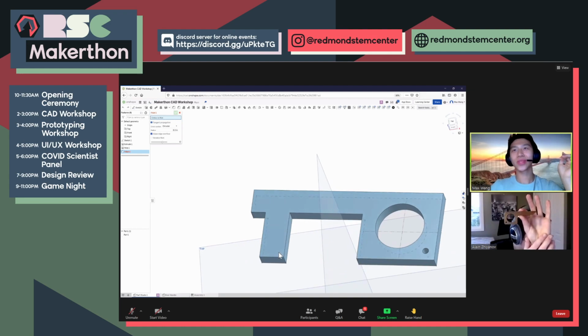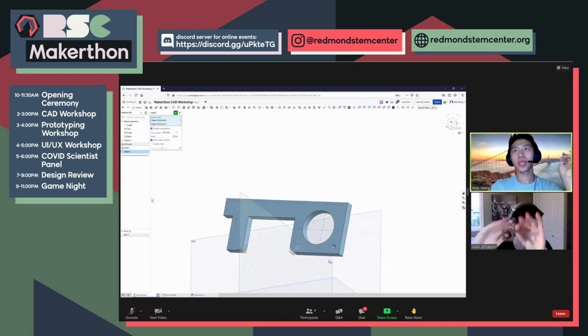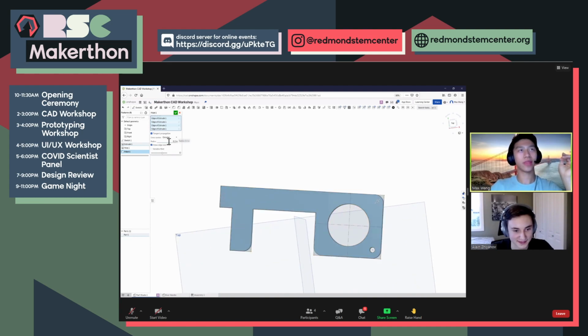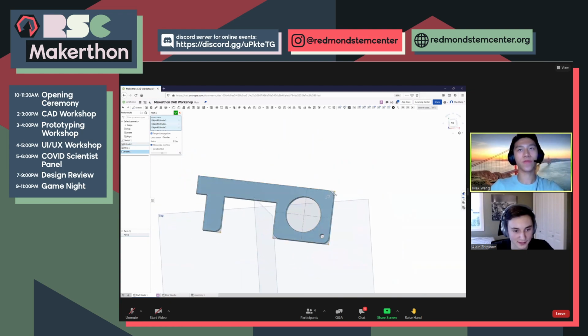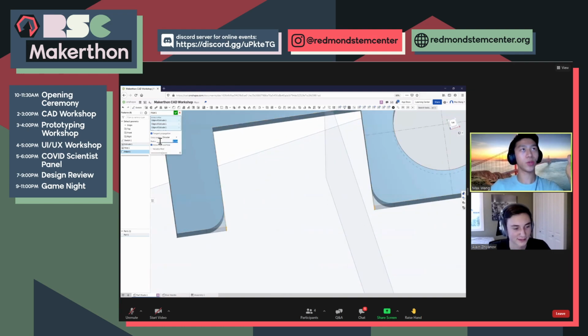So it looks like we want to fillet this edge, this edge, this edge, and this edge. Yep, those look okay. Basically, in the query box, it asks for the edges you want to fillet, and so that's why I selected the 4 edges that Alan's model filleted. And what this does, just as the graphic represents, is smooth these edges by a certain radius, which you can control here. Let's actually set this to like 0.4.